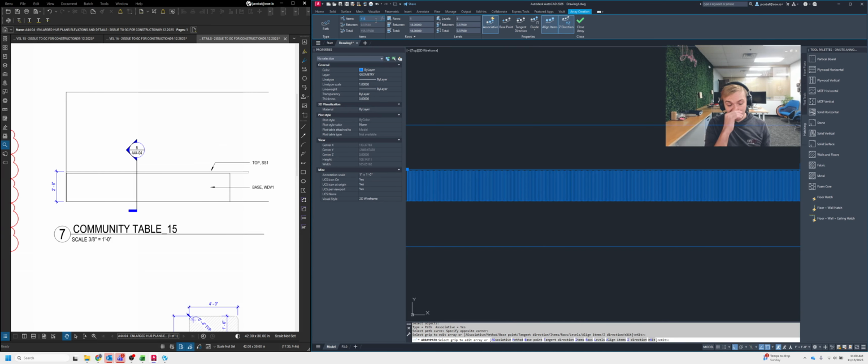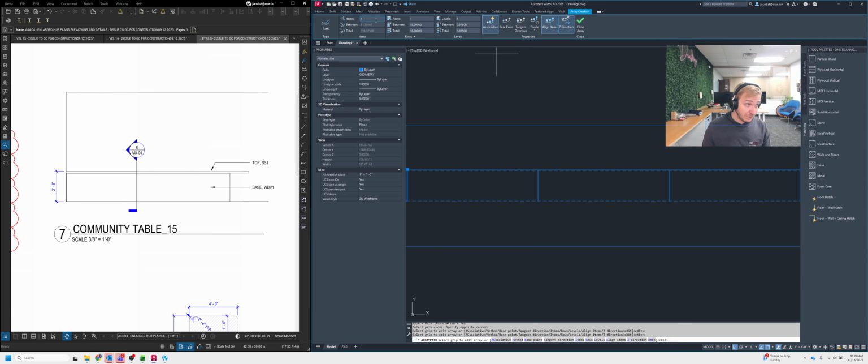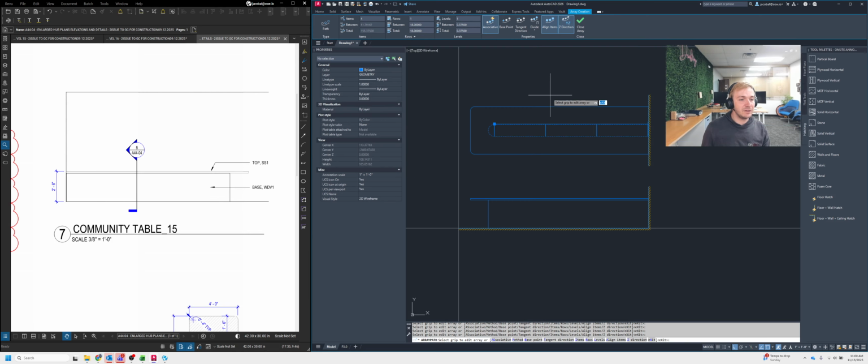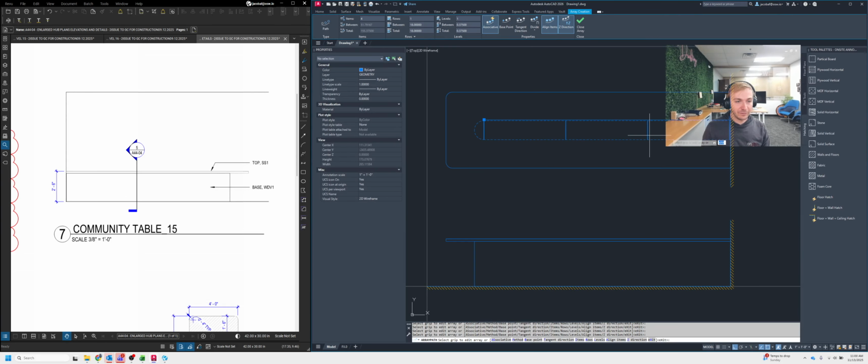And then you're going to adjust these number of items until you get to a place where you know you can make these panels work. So as mentioned before, I don't want to make my panels any larger than 48 by 96. So what I can do here is try to find a magic number that works. Right now at 3 panels or 4 reveal lines, I have a panel size of 51 and roughly 3/4 of